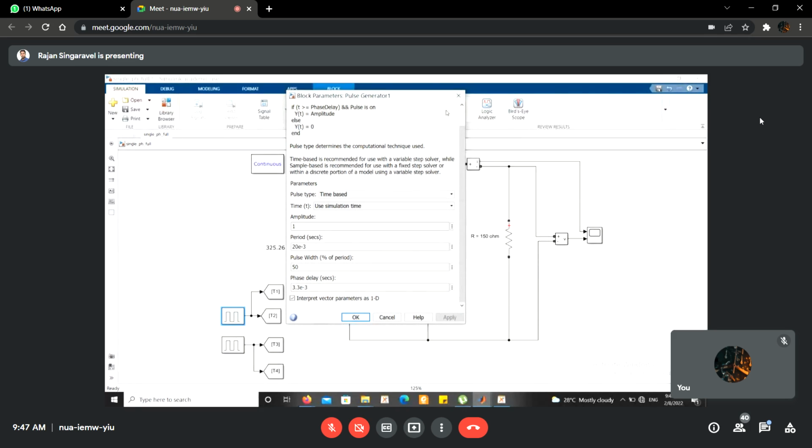But in practice, the pulse amplitude matters a lot; it should supply the minimum current to trigger the thyristor. As far as the simulation is concerned, the pulse is considered only as a signal, irrespective of the magnitude and the duration of the pulse. If it is a logically high signal, it will be considered a proper triggering signal for the SCR.